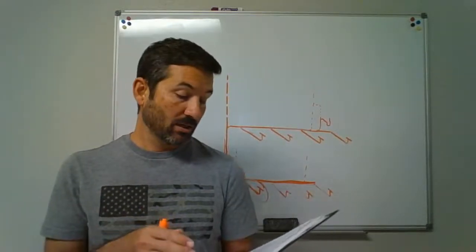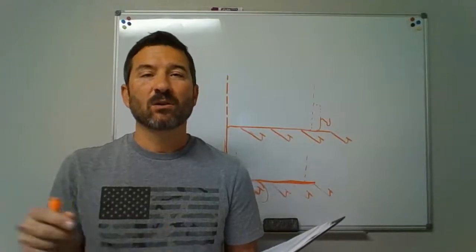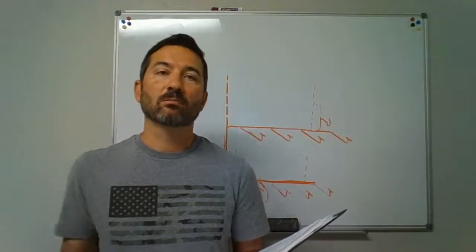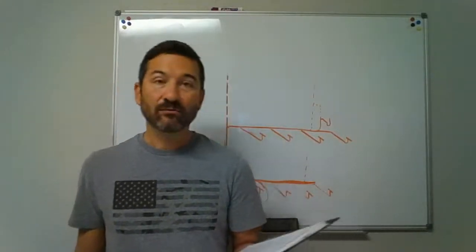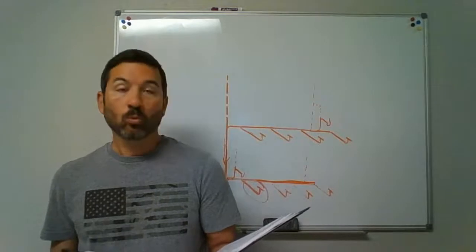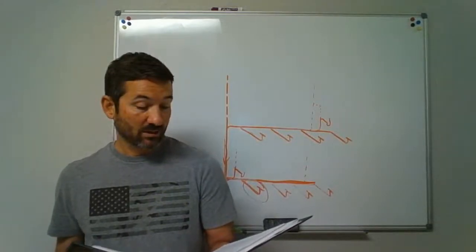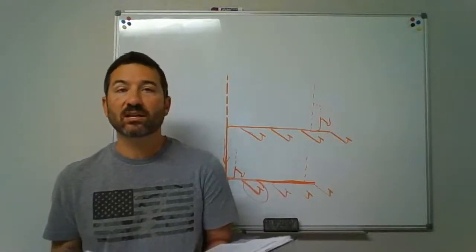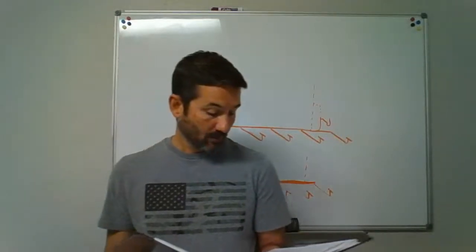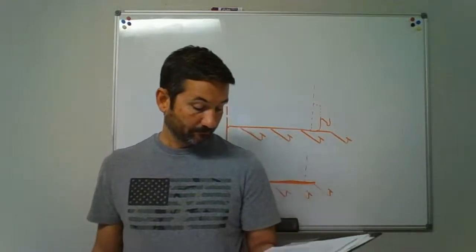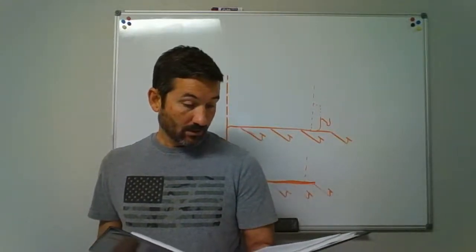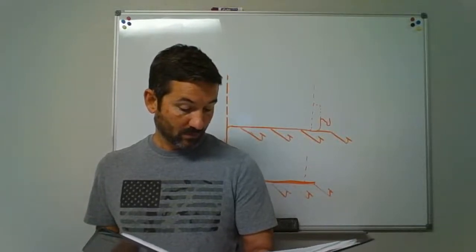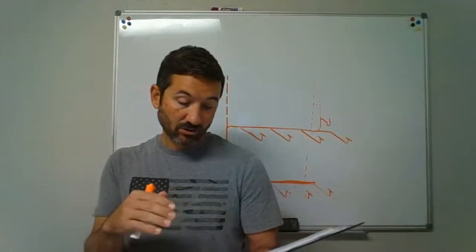Well, we can have a combination waste and vent system, which is basically taking a minimum size drain, increasing the size of it, and calling it both waste and venting. But we can't just come up with that on our own. It has to be plans and specifications for these. They have to be approved and obtained before any installation starts. It talks about some dishwashers. I'm going to let you read the rest of that section on your own.